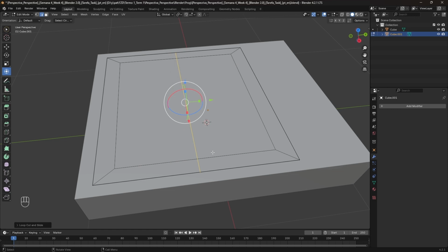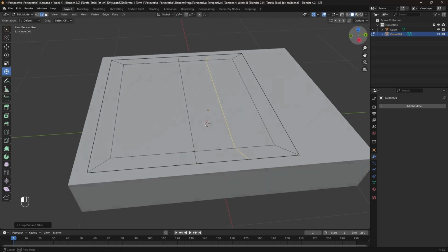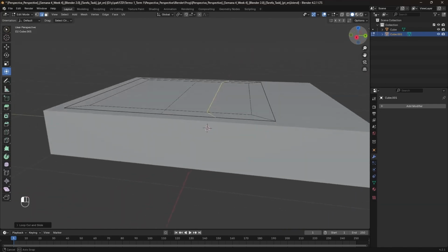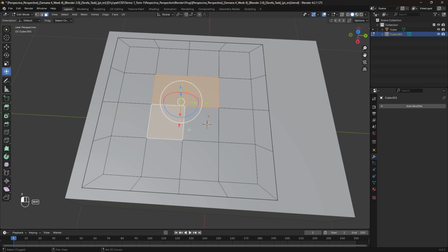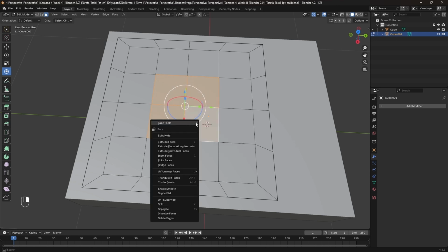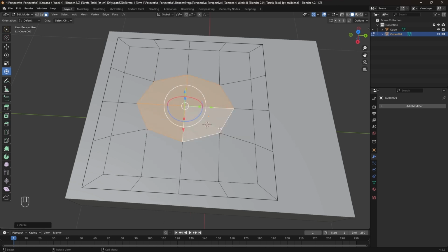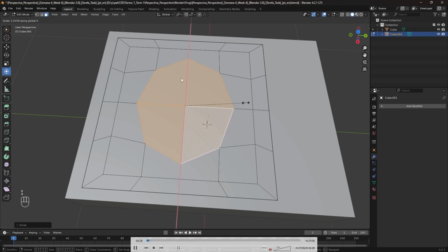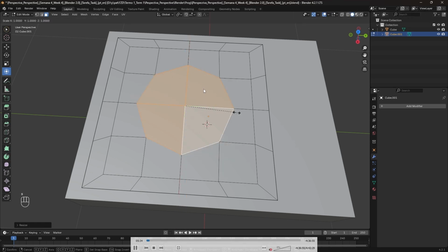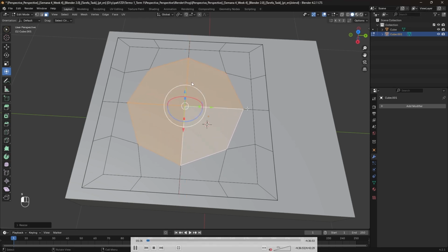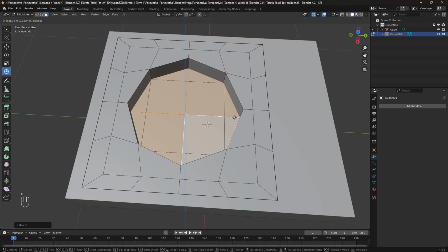My idea here was to create cuts so I'd be able to start mapping the stove burner region where I will place it. So I created cuts. After that, I selected these four faces. I went to loop tools and then circle. With this circle, I basically wanted to create the idea of a circle, and after that I scaled it, and then I extruded this face downwards. This way I was able to create this kind of behavior.